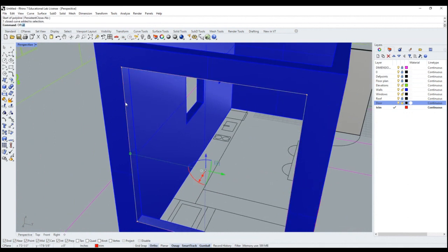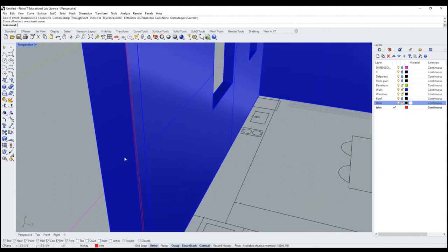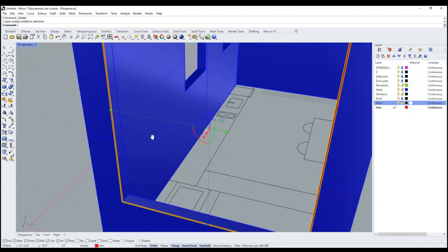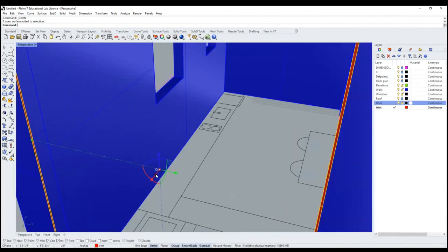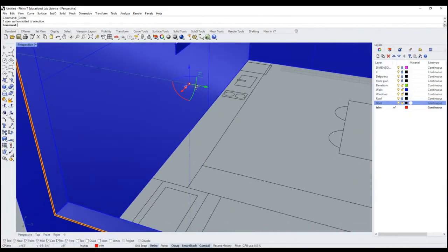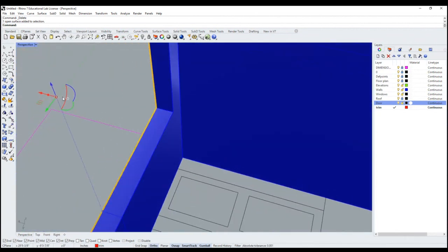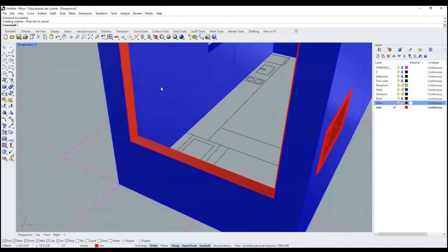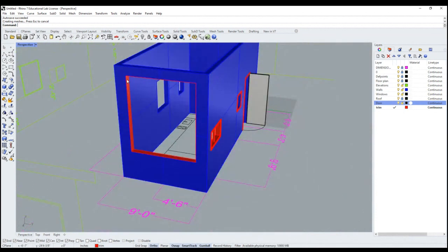So we're going to take this line, we're going to offset it 1/2 inch on the inside. And we're going to select both of these once again, planar surface, delete the line, take our surface that we have. We're going to use the red ball in the middle. We're going to drag it to the edge so that we get our extrusion. This is a short way of extruding all the way up into the edge to create that frame piece.